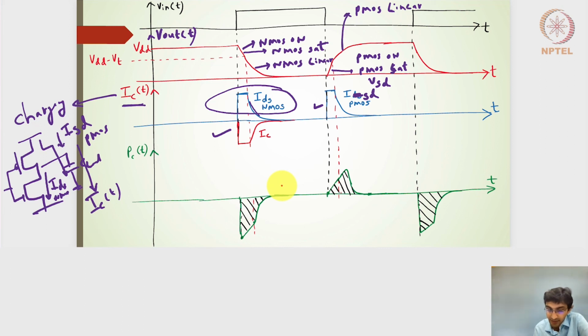And for charging of the capacitor, while the capacitor is actually consuming the power, this is the power while it is discharging, and this is the power of the capacitor while it is charging. So it is actually using that power to store the energy. In this case, it is linear here and constant, so I will have a linear profile up till this particular point. After that, I will have an exponentially increasing profile and then an exponentially decreasing profile. So multiplying these two, I will have a slight increase and after that it is going to decrease.